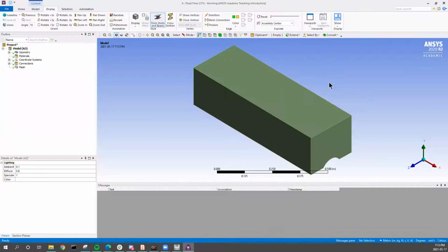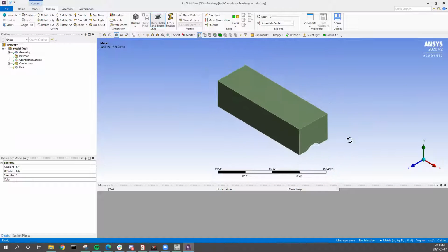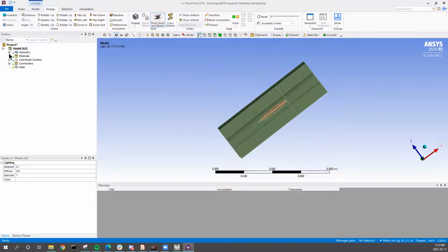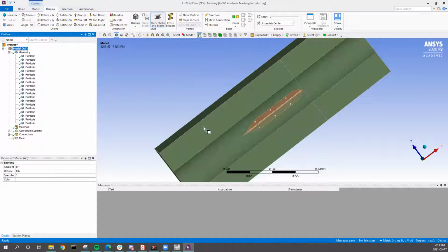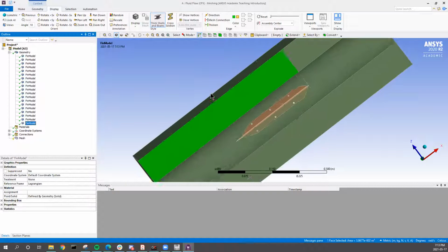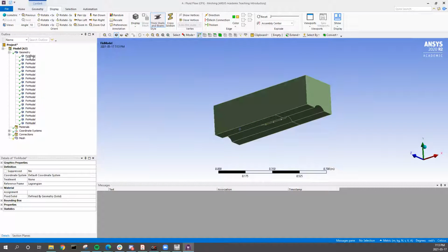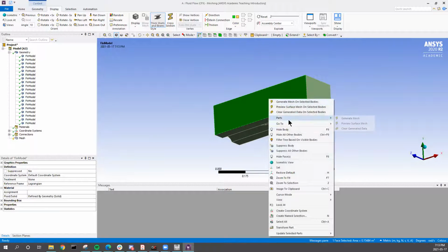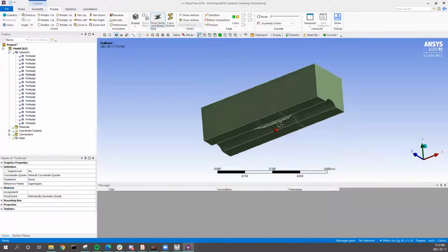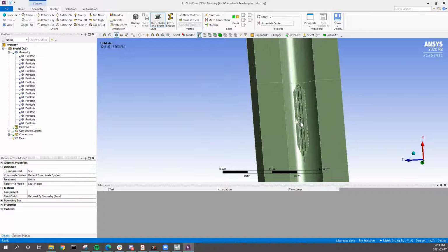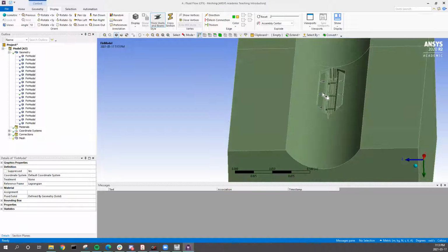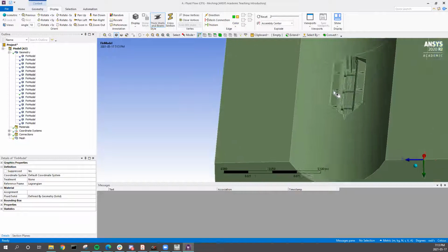Okay. Hopefully you guys can see this model now. It imports all the solid fin model and the fluid domain, so we basically need to suppress everything except the fluid domain. Unfortunately, we lost all the names, so I'm just going to have to click through and find it. Click on that, and then you can suppress all other bodies. So here's our fluid domain. It's this rectangle, which basically has a mold of the fuselage and fin. You can see it's cut out.